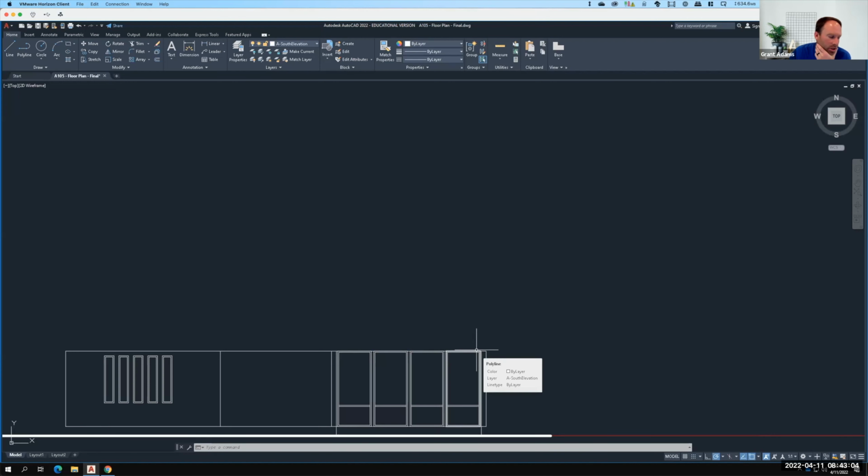And generally, this is listed as a rise over run calculation. So you'll hear a 6 and 12 roof, or a 12 and 12 roof, or an 8 and 12 roof. That means for every, let's do a 6 and 12, right? For every 12 inches of run, we're going to go up 6 inches. If it's 8, for every 12 inches of run, we'd go up 8 inches. If it's 12 and 12, for every 12 inches of run, we'd be going up 12 inches.